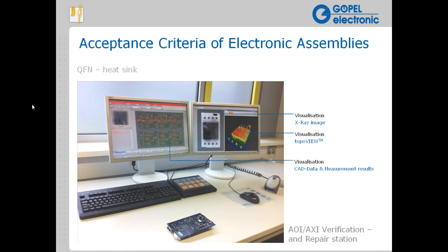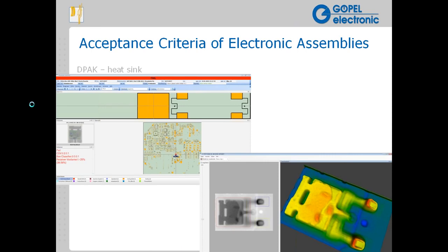To move on to a slightly different subject, THT, that's through-hole solder joints. These also can be quite challenging in AOI applications. In this particular image, you can see in the bottom center there is actually a pin that is not soldered. In the center part of the image, you can see a solder joint where the pin is not protruding from the solder joint itself, so it's not totally clear if the device is actually mounted there. And then on the left, you just see an unassembled hole.